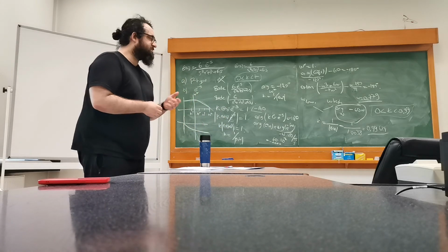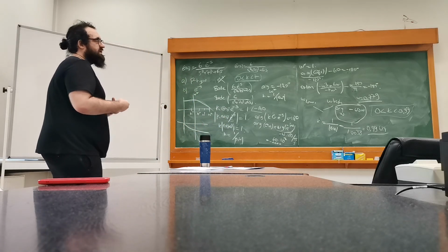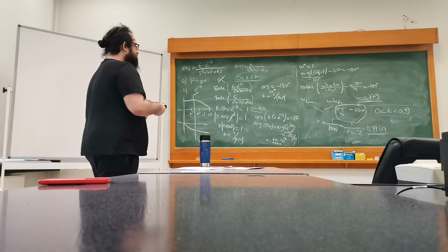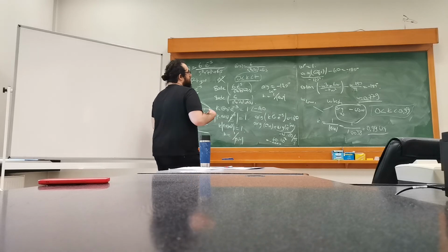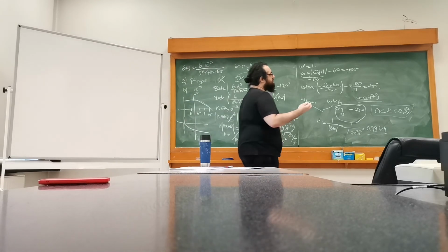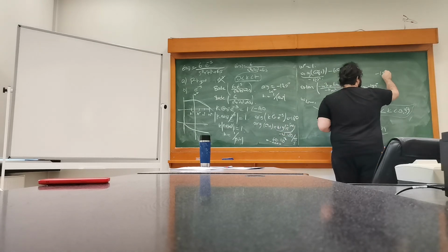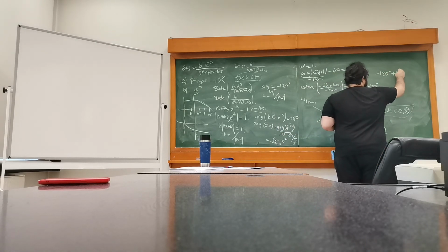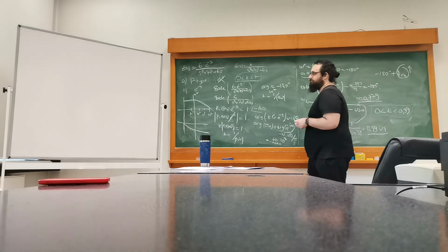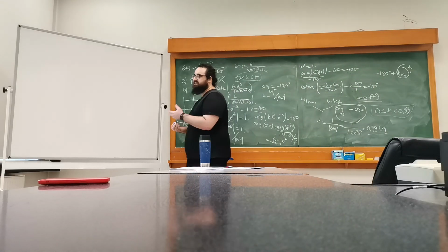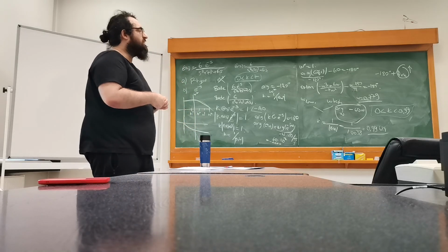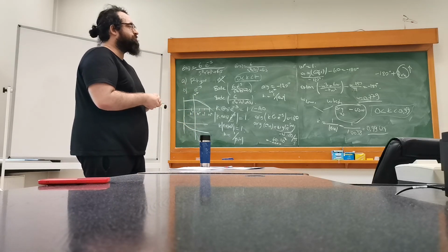If you add delay to the system, the stability decreases. Because we are safe if we are far away from 180 degrees. So the phase margin here, plus phi amp. If phi amp is high for a system, then you can compensate more and more delay, because you're far away from 180 degrees.